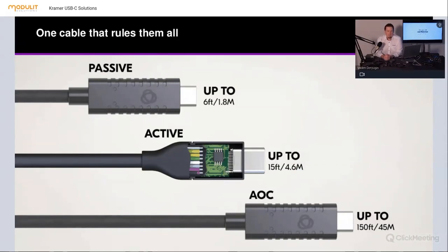All of them differ. First of all, when we are talking about the highest possible data transfer speed, we are talking about the passive cables, and the more bandwidth we need, the shorter will be the distance. So that's simple physics, and we cannot do anything with it. So if you need the highest possible data transfer speed, you should use as short a cable as possible.